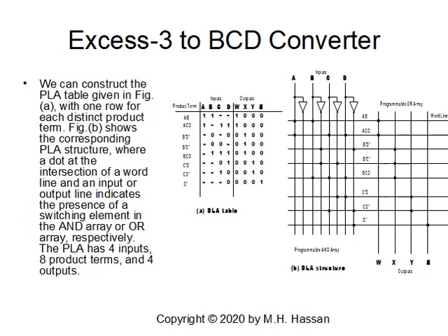But here we simplify the function and we implement each and every product term using the AND matrix. So everything is programmable, and this is a more efficient design because you will simplify the hardware to a very high extent. However, if you have a really large number of switching variables, the ROM would be the choice to implement any switching function. Now, this would be the last slide for this presentation.